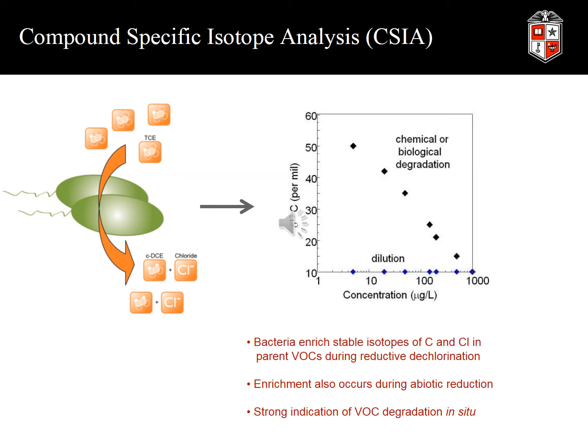The bioset beads that are used for microbial analysis can also be used to evaluate the isotopic composition of chlorinated solvents as well. The beads can be shipped to a commercial lab, they desorb the chlorinated solvents, and they can determine the stable isotopic composition of the chlorinated solvents. What this allows us to do is to evaluate the chlorinated solvents with depth to determine whether they're being degraded at high resolution, around every 20 centimeters, as well as what bacteria are present.